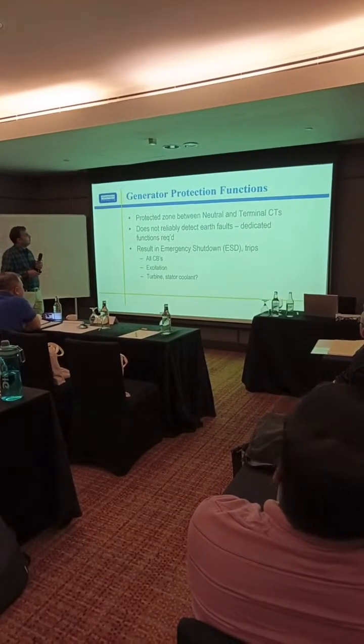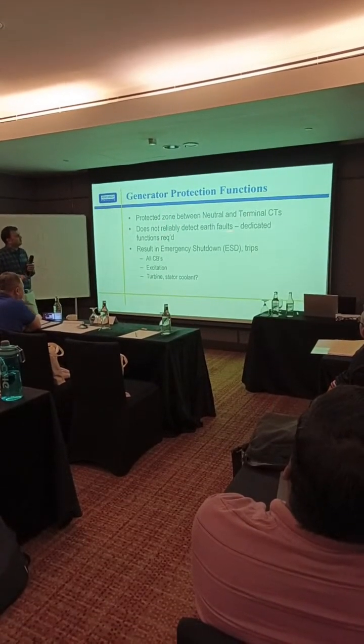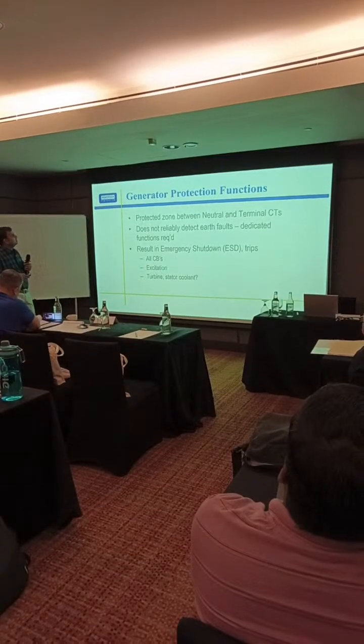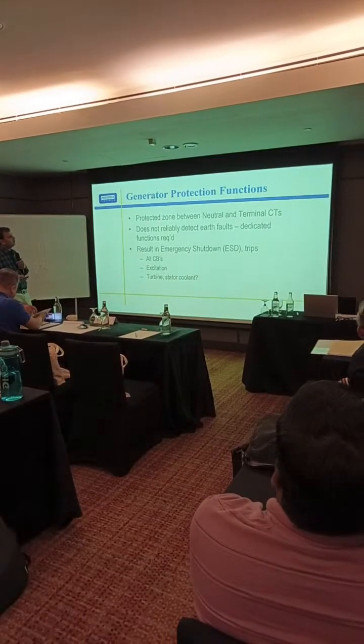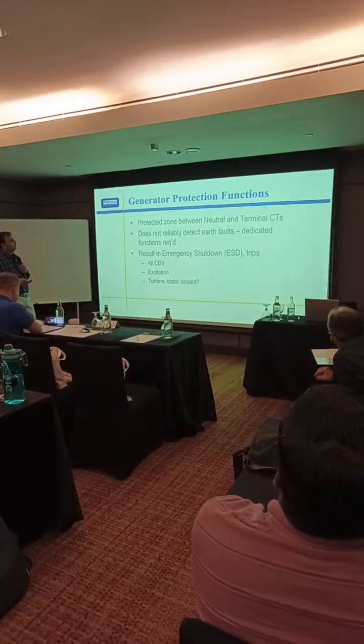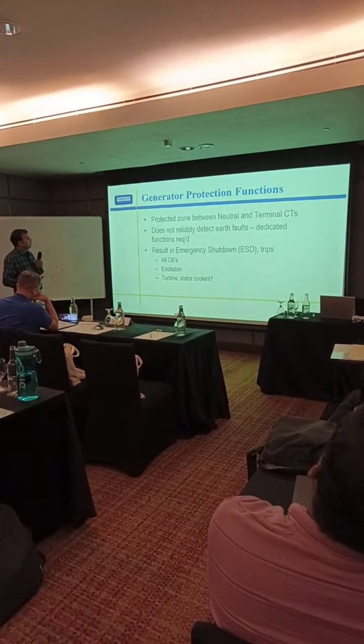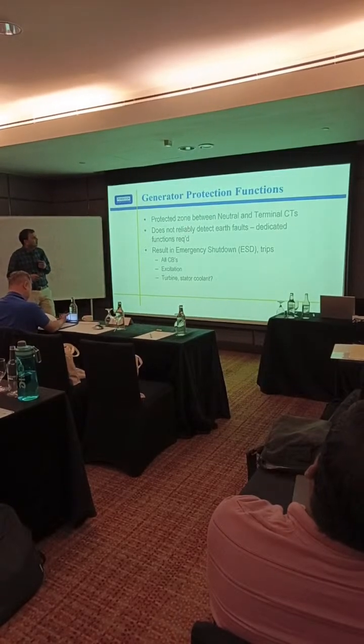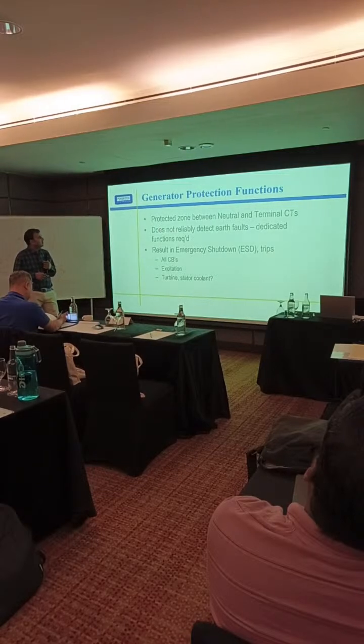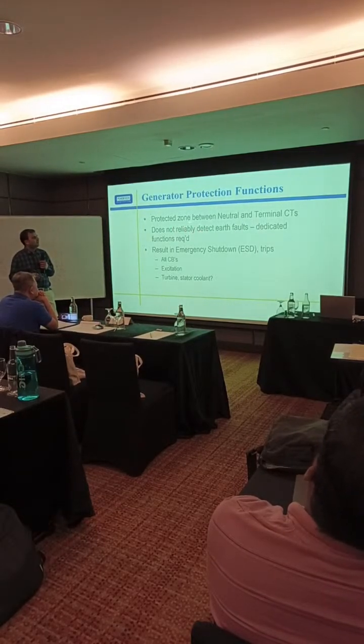So how does generator differential work in this? The protected zone will be between the neutral and terminal CT. And in generator protection, this is the concern: it does not detect earth fault reliably.